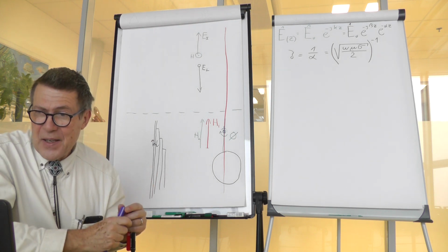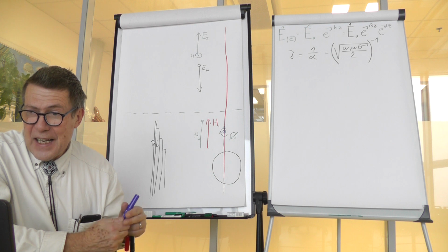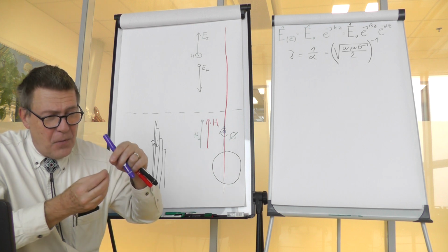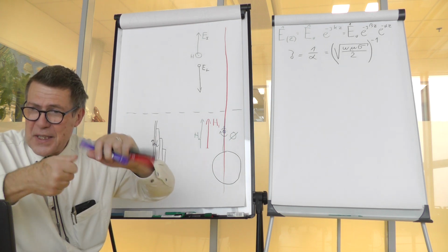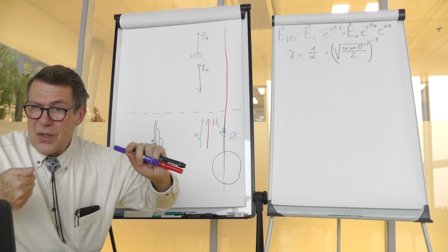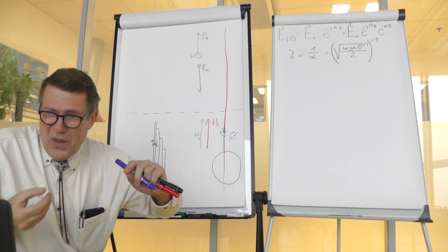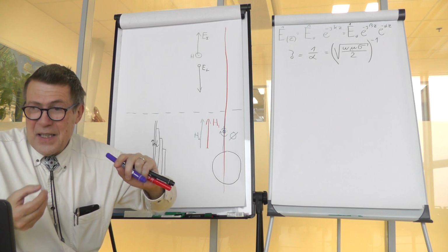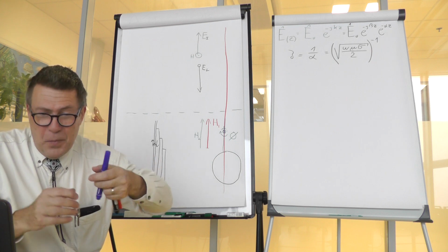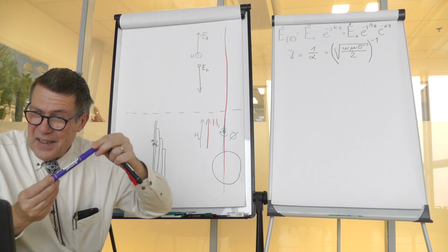not through the whole conductor, but only through the skin. And the solution for that is that you take a number of very thin wires and you just twist them, so that the surface of the conductors in this conductor is much bigger than would be a surface of a single conductor.